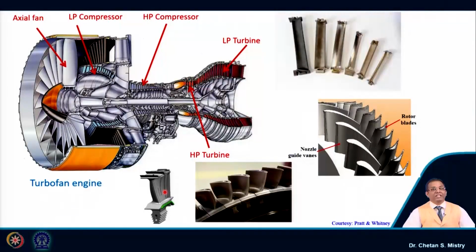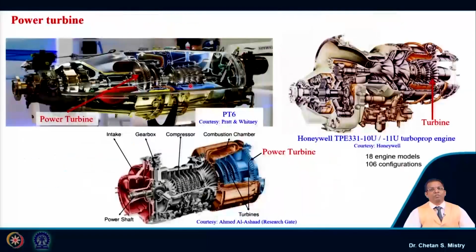So, basically air is used as a working fluid. Here in this case, since my operating pressure is higher, that means my injection of air for cooling purposes also needs to be supplied at high pressure. So, tapping is taken from the HP compressor, and from there it is supplied to my HP turbine. Otherwise, if we took a low pressure entry, then my flow would go in reverse, from the high pressure side to the low pressure side. So, that is how the cooling arrangement is made. Okay. Now, let us move to the next.